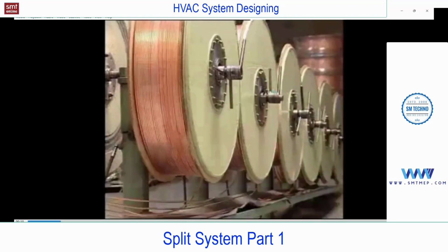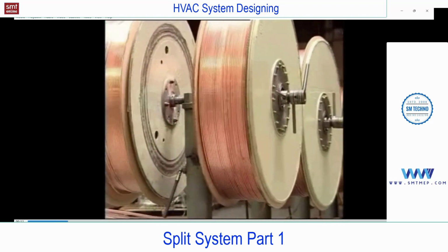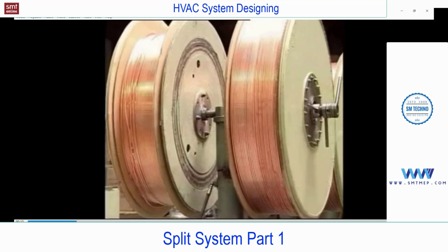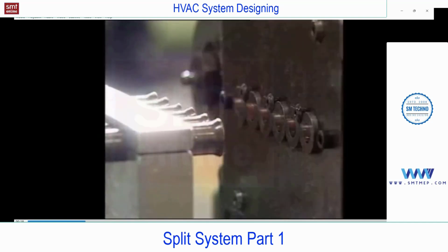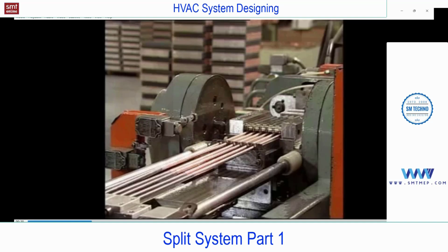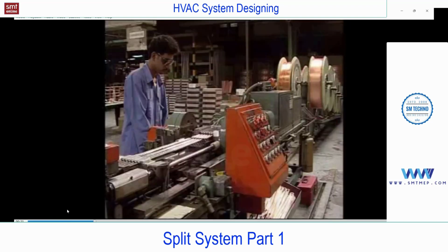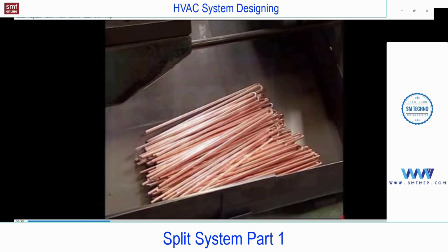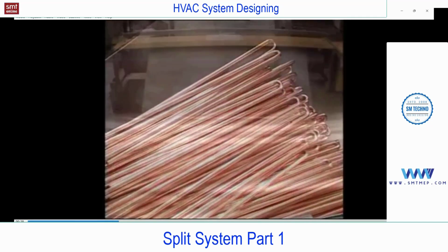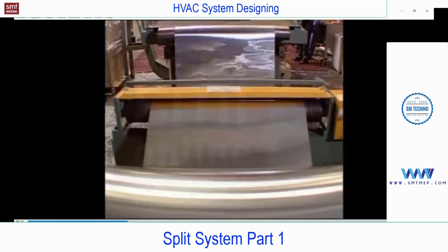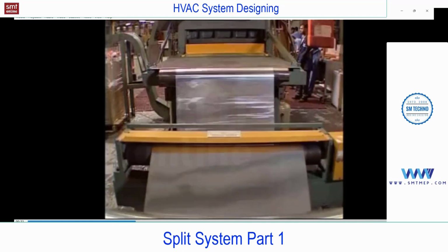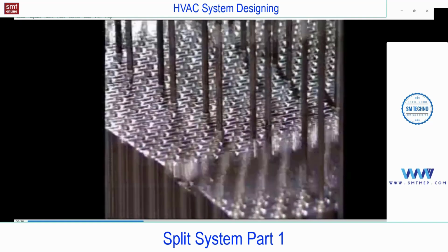Changing from smooth bore copper tubes to internally enhanced inner groove tubes enables a move towards higher efficiency heat exchangers. The process of coil making includes the drawing process. And remember, the copper tube is a seamless pipe, not a welded pipe. Hairpin tube cutting and bending machines draw the tubes from the copper reels, cut them to the required length, and bend them 180 degrees. Alongside is the fin pressing, where the punching of holes, corrugating of the surface, and cutting to the required dimension take place.